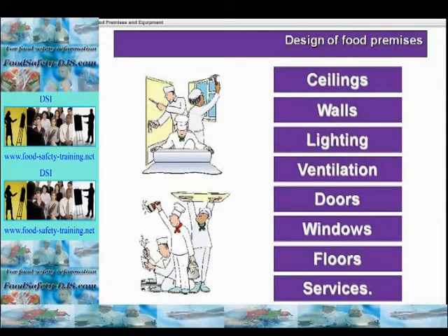Doors and windows: there should be self-closing doors, with handles to allow disinfection. Pest-proofed, and fly screens are necessary, especially on openable windows, and avoid glare, windows preferably north facing. With services, pipes should allow access for cleaning or be concealed, or flexible where feasible. The use of waterproof sockets should be considered. There must be an adequate supply of potable fresh water and an external water supply. There should be adequate drainage, trapped gullies, and they should be pest-proofed.